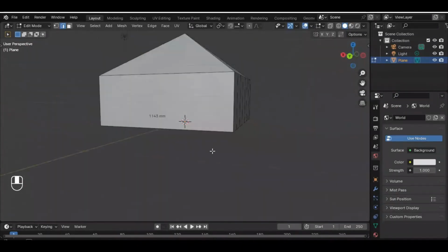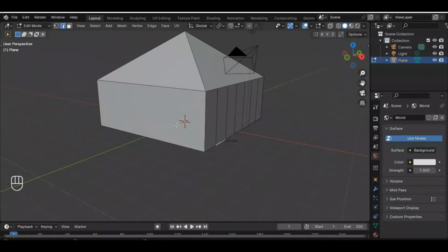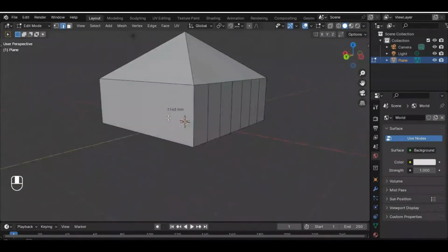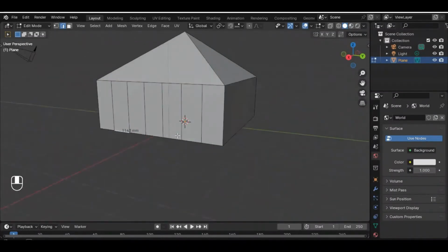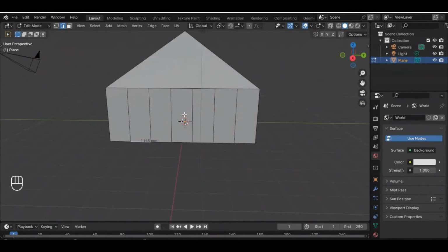So it's cutting along the entire mesh. Cutting around, that's what the loop cut does. If these meshes are not connected, it's not going to cut the whole thing. It only cuts whatever is connected. It doesn't cut what is not connected. So what we want is to get a door hole here. So let me look at this. I want my door hole to be, let's say, 1,200 or something.